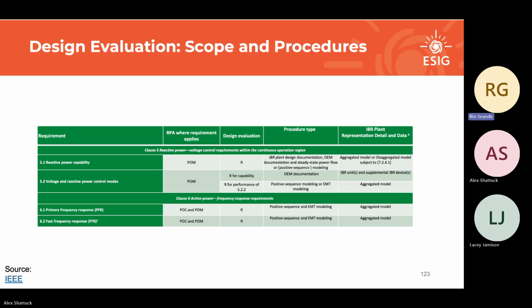Pretty much just for wind, basically. Because what happens, especially on the inductive side, is when you try to design a plant to meet a power factor requirement to capacitive, you're really struggling to get to your 0.95 power factor. On the inductive side, you're usually blowing past 0.95 power factor, and you have a lot more capability, especially at wind, because it's inductive plus the losses. And that can really drop your voltage at the farther inverters, at the farther turbines. And that's why ERCOT's Schedule 3 testing for reactive power testing is really important: that's the test you can do in the real world.